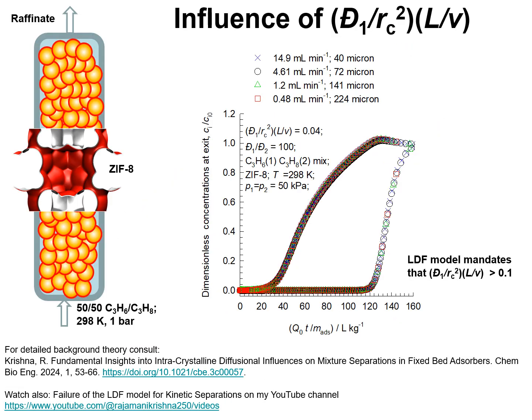We've established the optimum diffusional time constant and the optimum contact time for increasing the productivity of purified propane in the adsorption cycle.